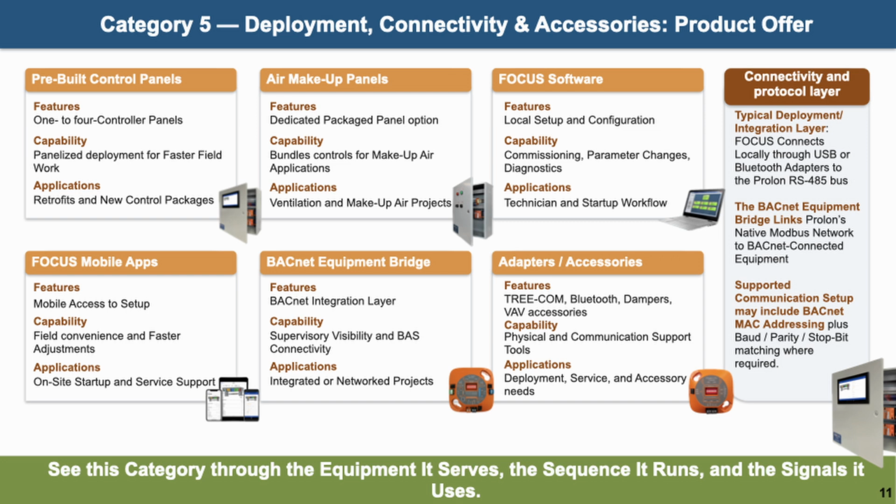These products do not replace the controllers or sensors. Instead, they make the total solution more practical in the field. This category supports cleaner installations, faster startup, better diagnostics, and improved system visibility. Focus can connect locally through USB or Bluetooth adapters to the Prolon RS485 bus. The BACnet equipment bridge links Prolon's native Modbus network to BACnet-connected equipment.